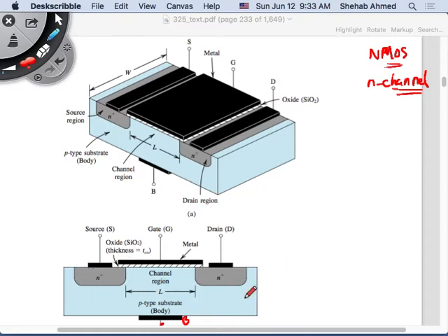So I have a P-type substrate, meaning what? Meaning it has majority holes, right? Did I put acceptors or donors into the semiconductor to create P-type material? I put acceptors, so that any free electrons are bound. And then silicon is left with some holes that can be filled or used for carrying charge, right? So the majority carriers are the holes. The minority carriers are the electrons, in the P-type material, right?